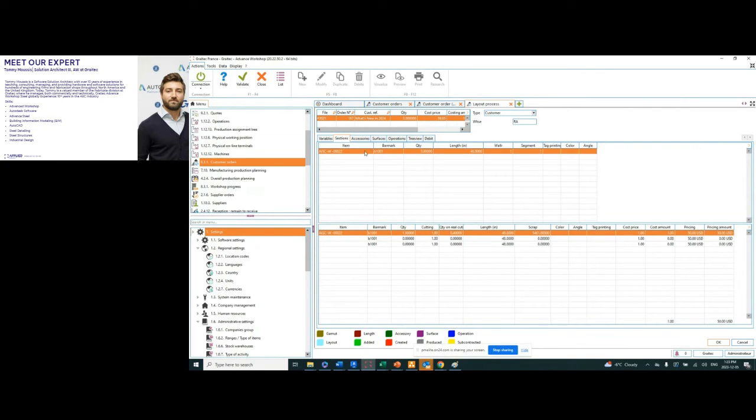So depending on the bar element, here, once again, I have 3 bars that are the same. So it's showing me the quantities that I would need to purchase. So it's 1 bar in short that I would need to purchase to accommodate all lengths. And then here we'll see the waste material.